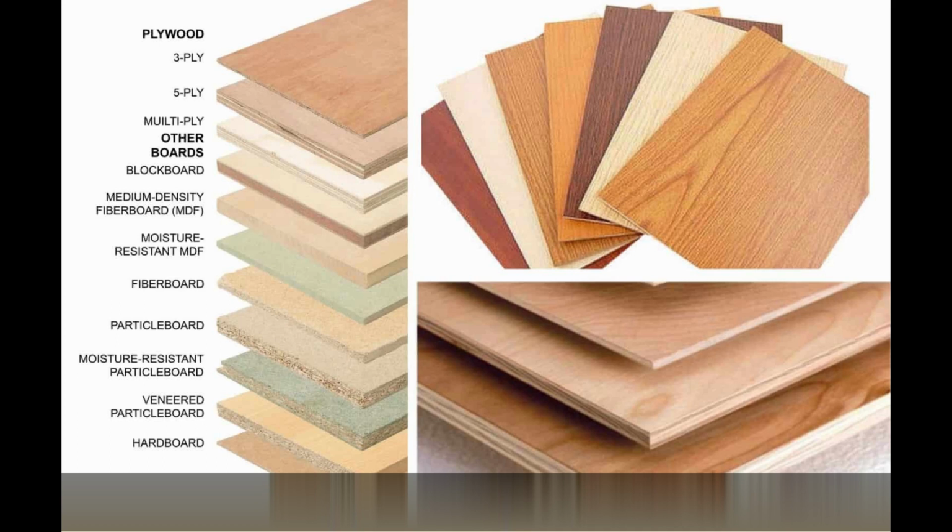Roofing can use the thinner 16 mm plywood. Some floors are at least 19 mm thick, the thickness depending on the distance between the floor joists. Plywood for flooring applications is often tongue and groove.